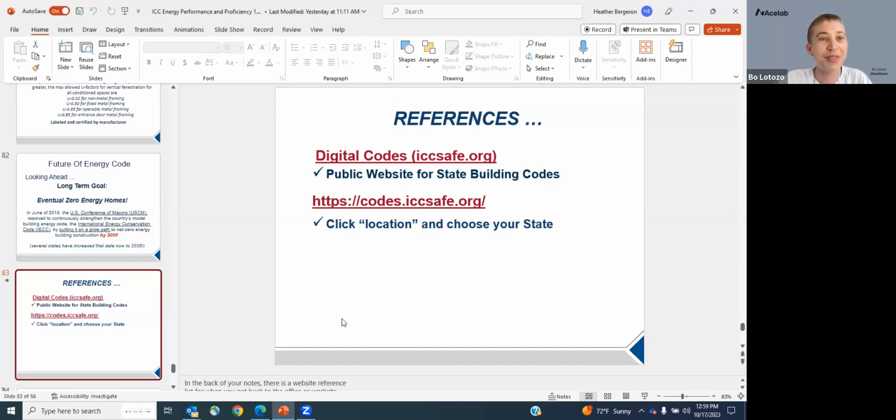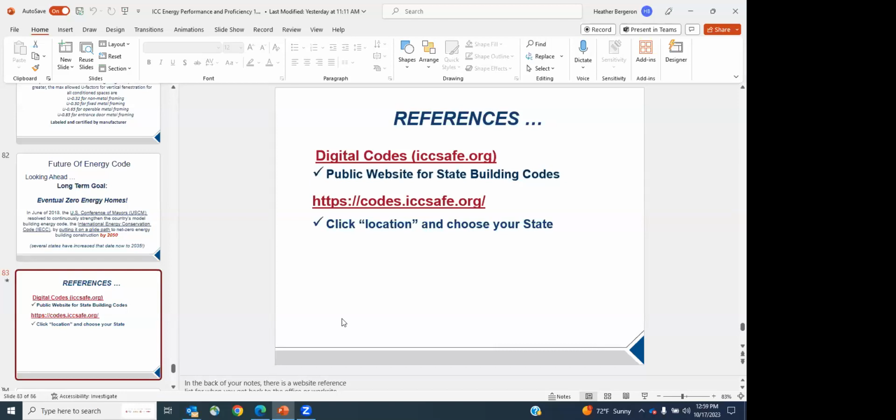Let's see, one more real quick, and then we'll let everyone go for today. So does a low E coating work in different temperature zones? And if so, what surface would it go on? The answer very quickly is yes, it does work in all different zones. What surface we put it on will depend on where the product is going. If it's in the south, generally it's going to be on surface number 2. That's counting from the outside, always count from the exterior.